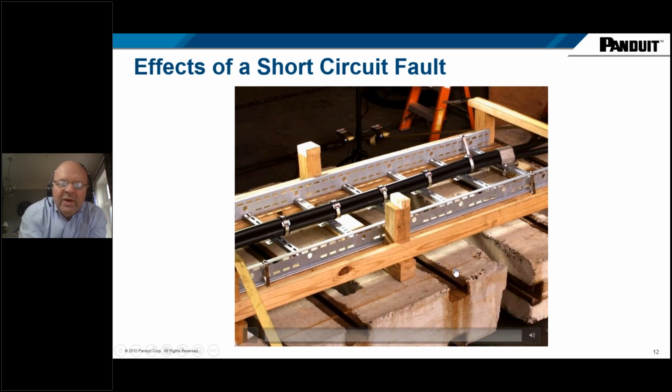And what we've done in this situation is to show you what will happen when the cable cleats installed are not strong enough to withstand the forces that are exerted by this short circuit event. So what you will see here in this video is the cables will try and get away from each other, and they will fly off in different directions, and the cleats installed are insufficiently strong to contain the cable. So I'll just run the slow motion video.